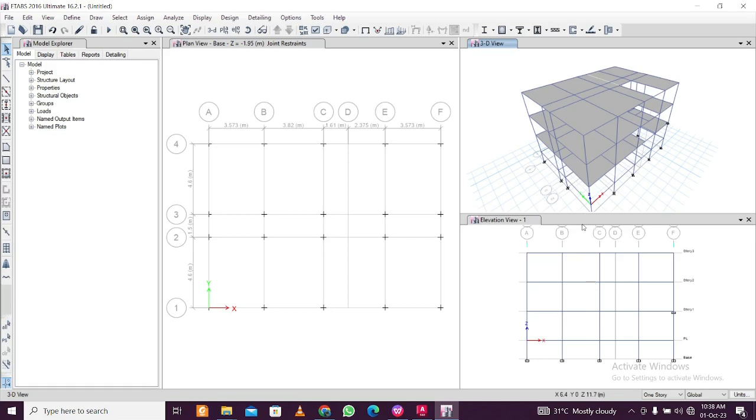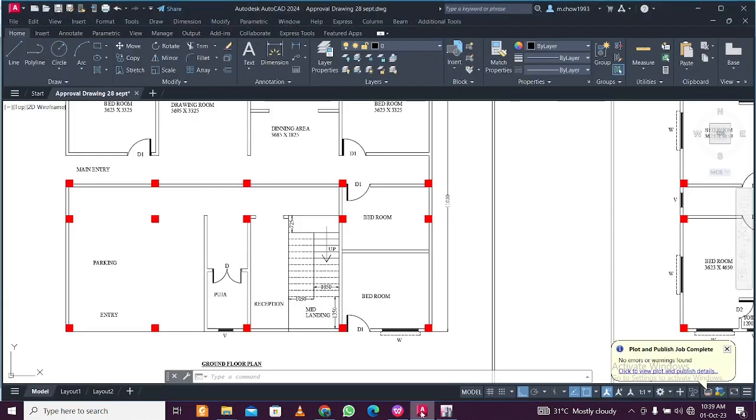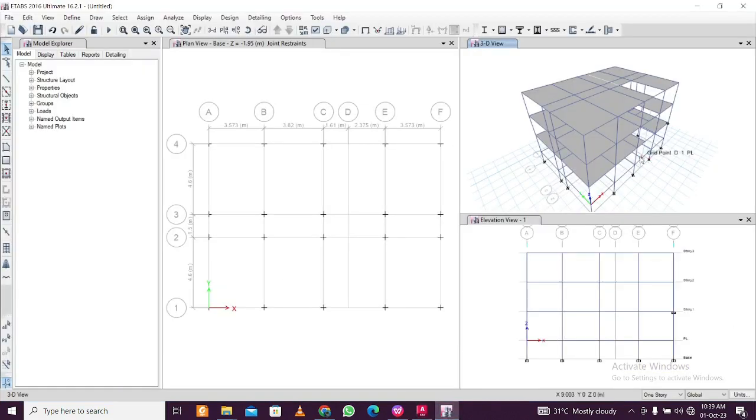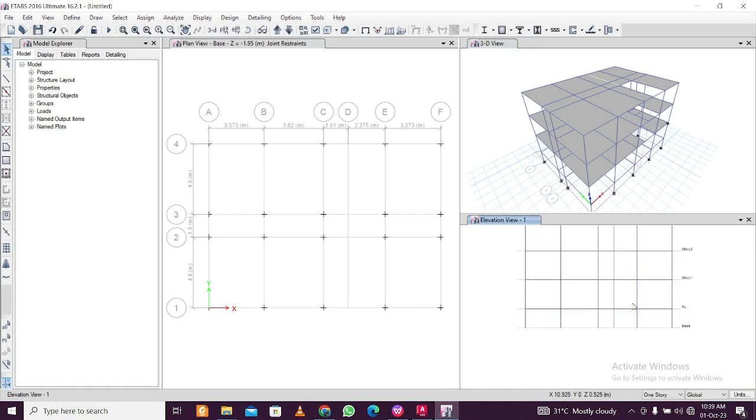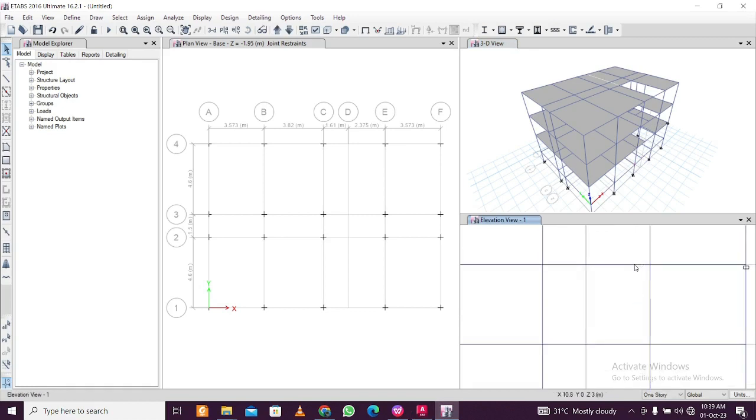You can also relate it with the theory of design of staircase, which you have studied already, I believe. So we'll do that. You can see the staircase is here. We will see in the architectural plan, the mid landing will come in this particular portion, around here in this grid, that is the grid 1. So you can see the grid 1 is here, and if I select this particular beam and copy it down below, then I can create this.